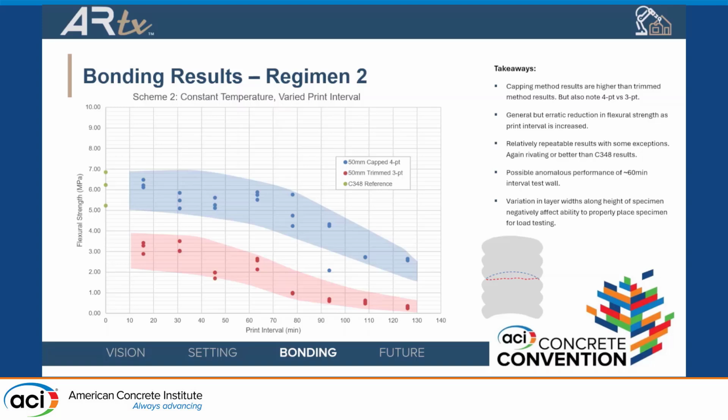So those are illustrated here. There's another factor at play there. When we vary the interlayer time, the amount that the bottom layer compresses will change. So that profile is actually not constant that we draw as the interlayer contact.